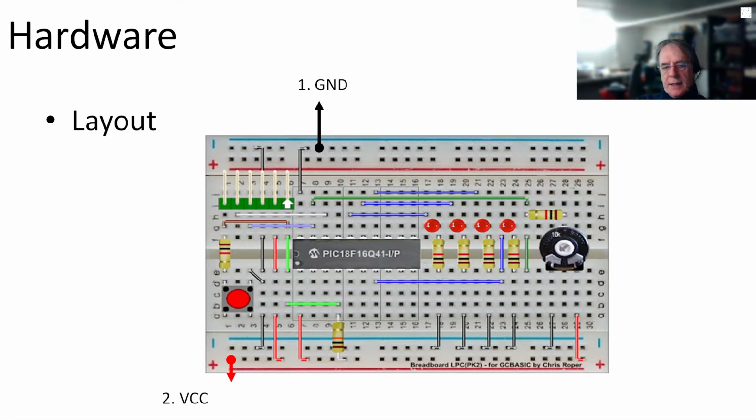Two things I'm not going to connect in and show you today in any depth are the ground and VCC. They are very specific to your SPI device. Make sure they're connected up adequately and you've got the right VCC.